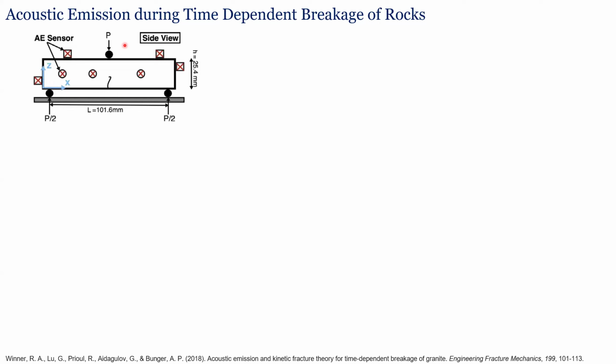And so one of the things we got interested in was how do rocks break in a delayed manner? So instead of just loading it until it breaks instantly, what if we find where that instant breaking load is, but don't go all the way there? We go to a load that's maybe 70 or 80% of the load that it would take to break the rock instantly, and then hold it. And during these series of experiments, we measured acoustic emissions during the lead up to failure.